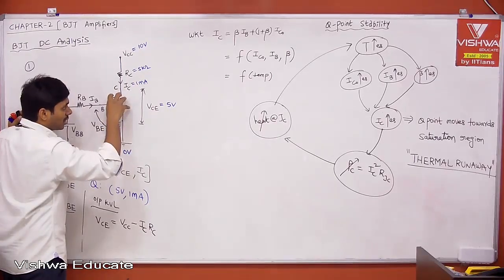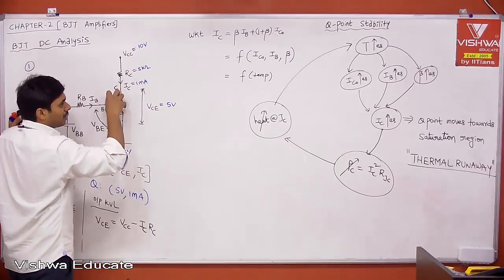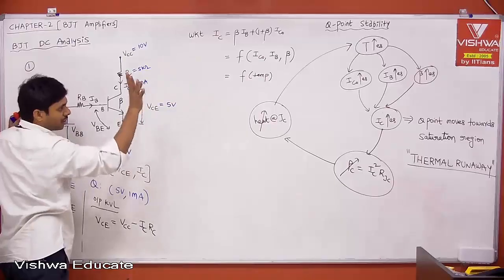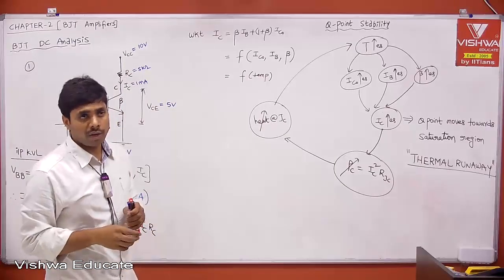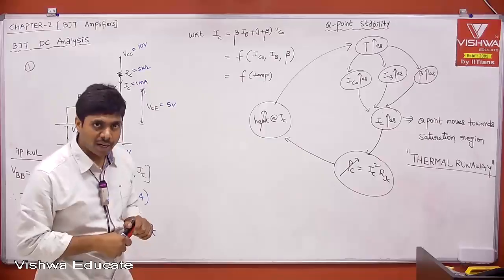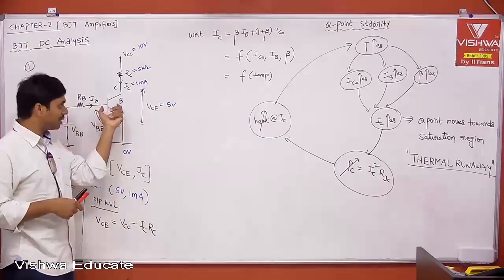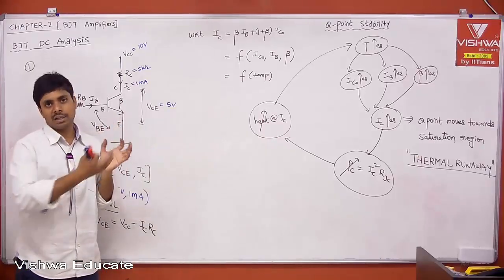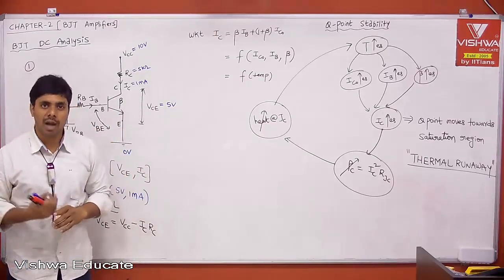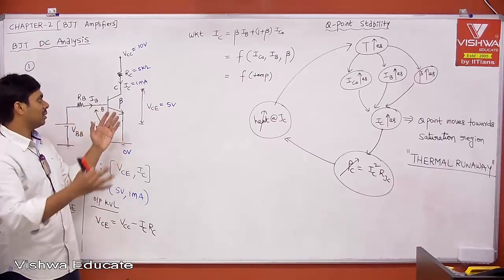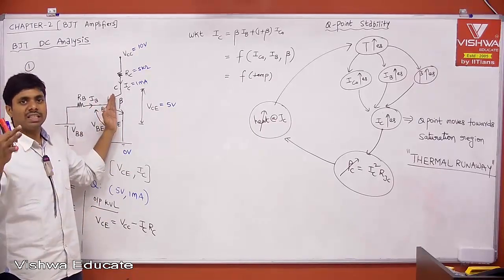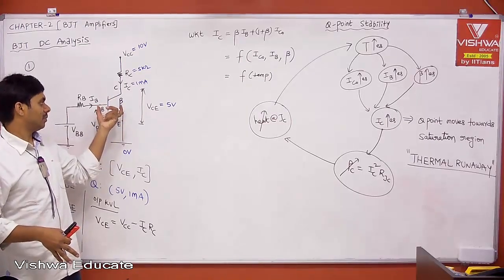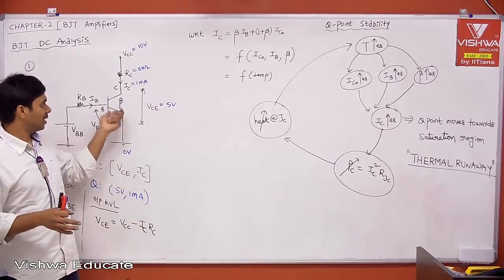Then the heat energy whatever you are getting, that is increasing. If that increased heat energy is dissipated safely into the environment, if there is no heat energy accumulation, then your temperature will not rise. That is an important point. We will not see temperature rise, provided the heat energy you are getting from the transistor goes into the environment safely. If there is no heat sink, where the heat sink is not taking out the heat energy, then there is a delta between the heat energy at the transistor and the heat energy in the environment. If the heat energy is increasing,